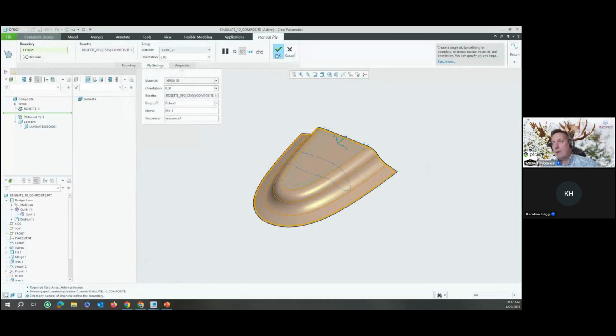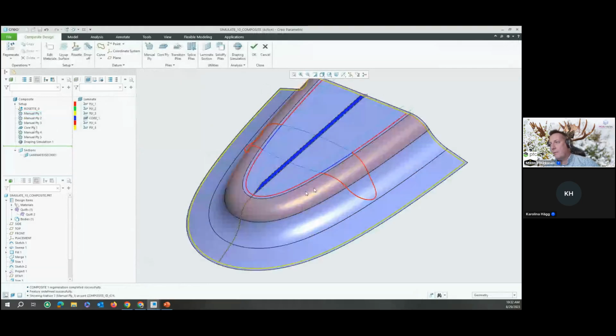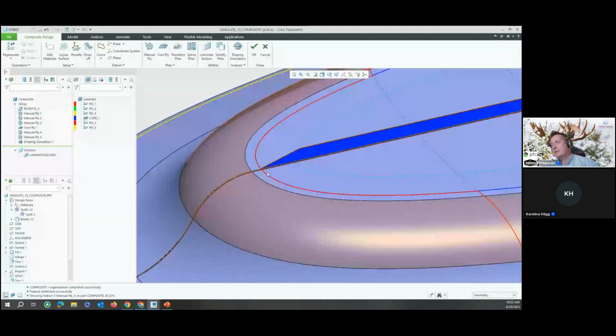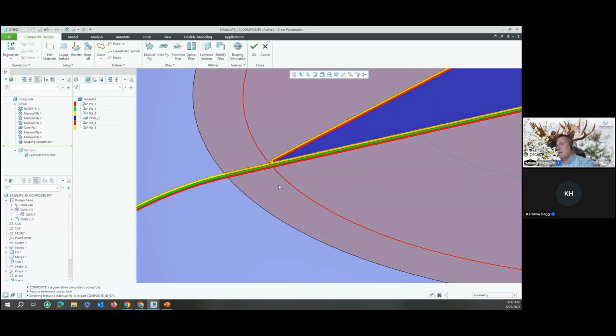And then just go ply by ply higher and higher. And when you do make a laminate, and if I zoom in heavily, you will see different colors now, which first of all represent the laminates on the model tree, but also you will see the thicknesses. Since sometimes these things are something like 0.2 millimeter thick, they start to be quite difficult to see. So we can also scale the thickness in the thickness direction so that you can really see. And it's also quite beneficial to see, okay, what does my laminate look like?